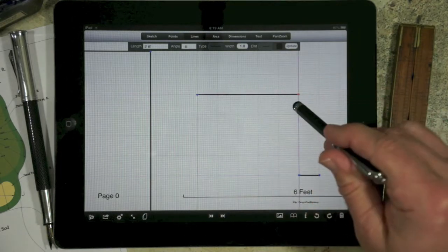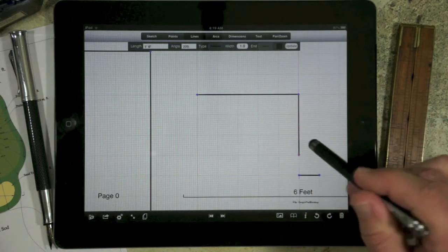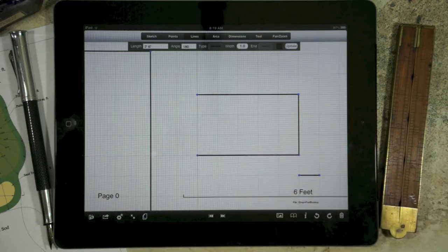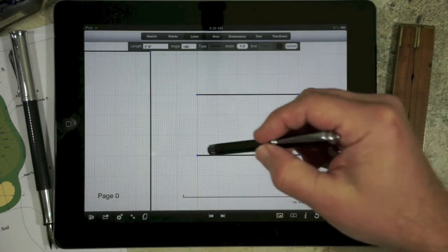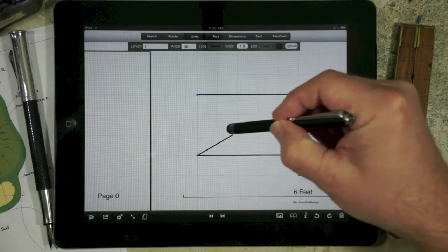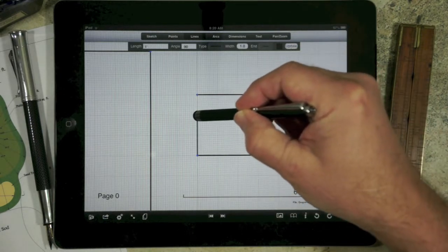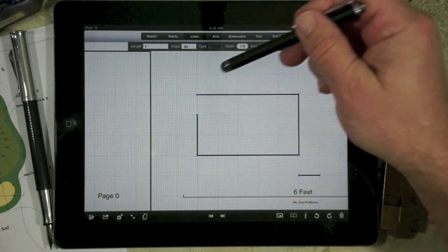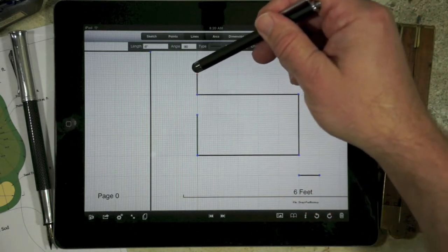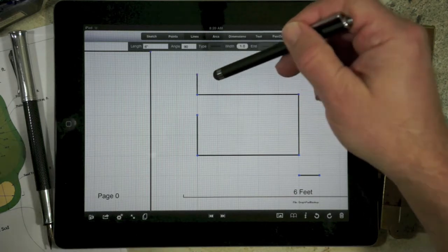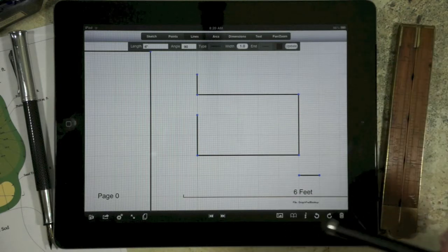We'll notice as I draw that it's precisely on the grid, and that's because of this grid size. Halfway distance between the grid size, it's going to look around for the point, and you'll notice that I was able to grab that point even though I was nowhere near it. Similarly, hopefully this will show up in the video, I'm way up here, but it says, okay, obviously I was trying to get that particular point.